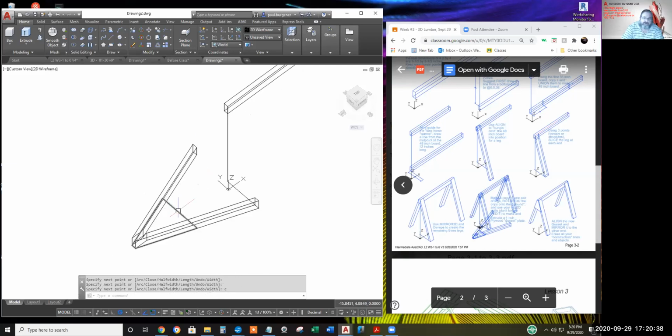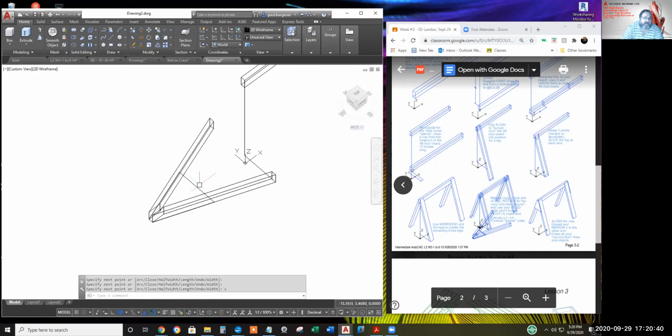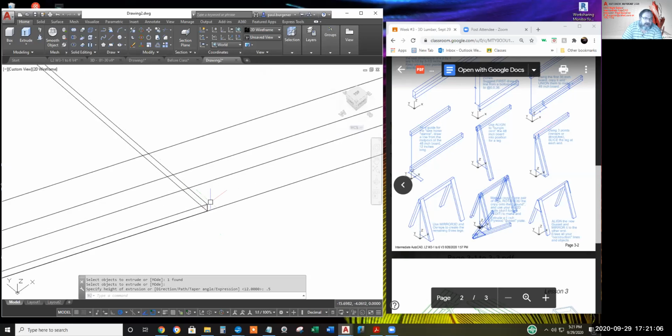Now, can I extrude this straight down? I think I can. Extrude, select the polyline gusset plate we had, hit enter, slide my cursor in the negative Z direction. How thick's the plywood? Does my handout say? 1/2 inches we got left at this construction site. So I'll type 0.5 and hit enter. And darn it, why did it go up instead of down?